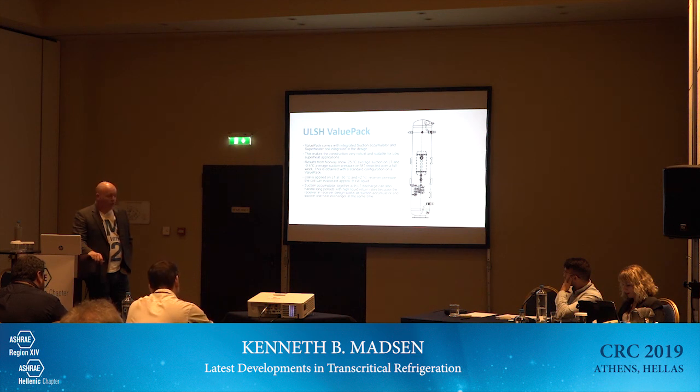So in Norway, we have a small supermarket running minus 25 evaporation on low temperature and minus 0.4 evaporation on medium temperature. So quite high suction pressures achieved in this study.